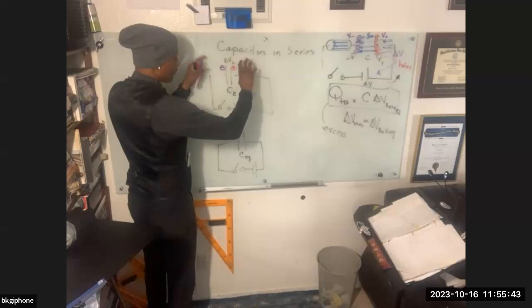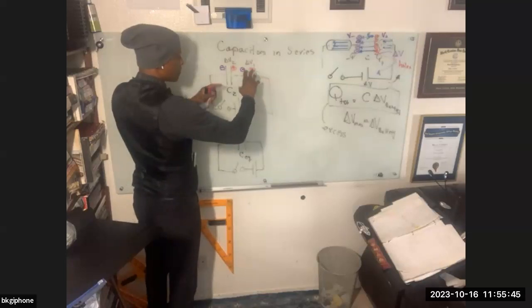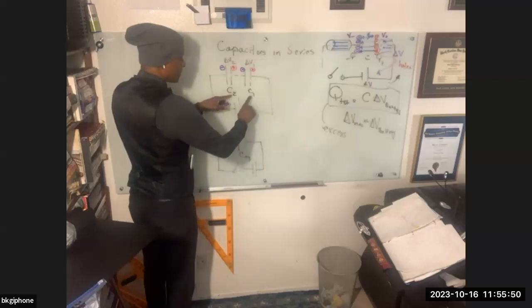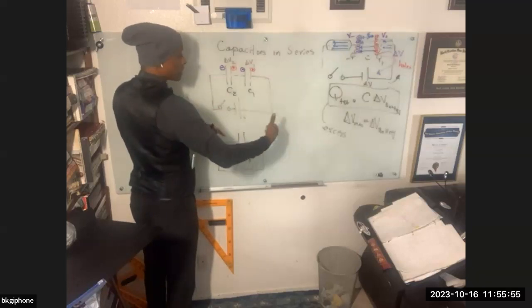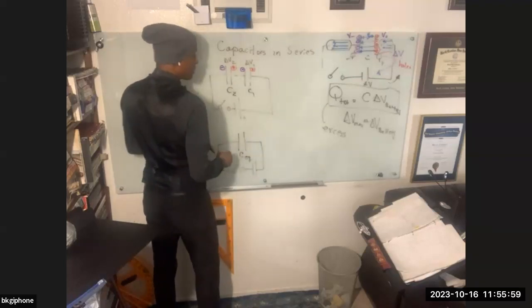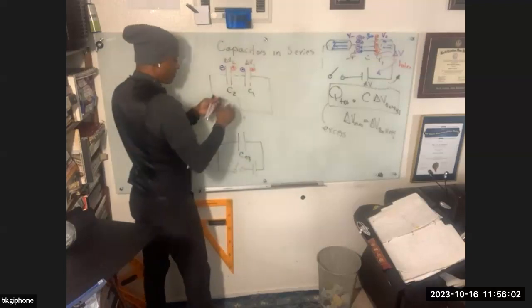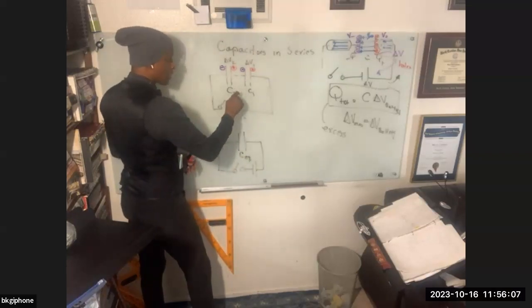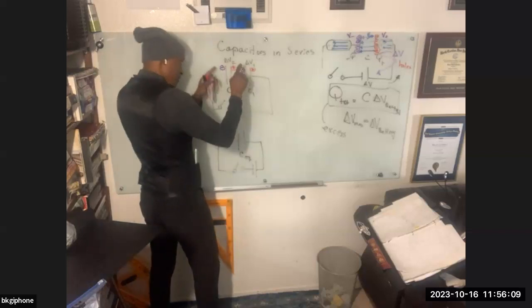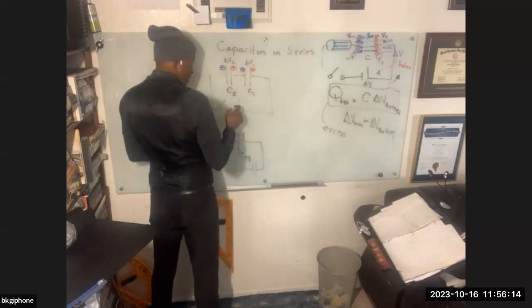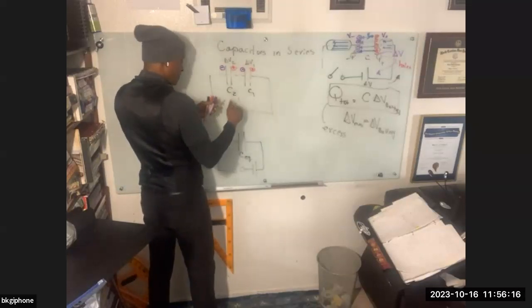And so we start to see the voltages created simultaneously. Now, they're not necessarily going to be the same voltage. They only will be the same if the capacitances are chosen to be the same. If the capacitances are different, then the ratio of charge to voltage is different. So the voltage is different, and the E fields in there will be different as well. But what is the same, even if I choose the capacitances to be different, the voltage is different, the E is different, is that literally I'm pulling one charge off and putting one on, it's happening simultaneously.